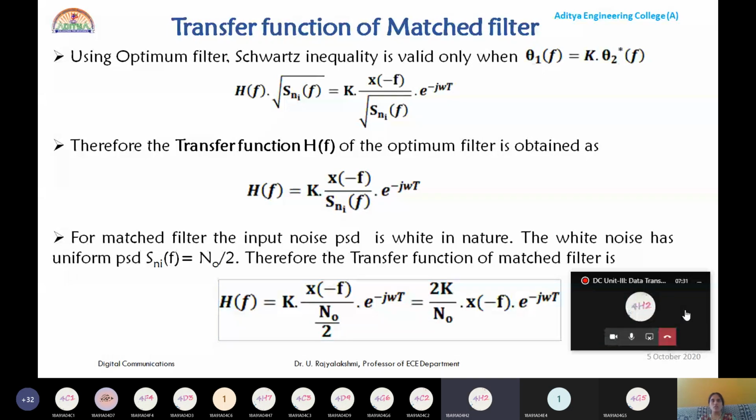Rho is x0 square of t divided by output sigma whole square. Yes, very good. That is the square of the output SNR. With that internal factor, we assumed it as rho. Rho square, which is x0(t) by sigma whole square, where x0(t) is nothing but the change in the output signal, and sigma is the standard deviation, and sigma square will be the variance.